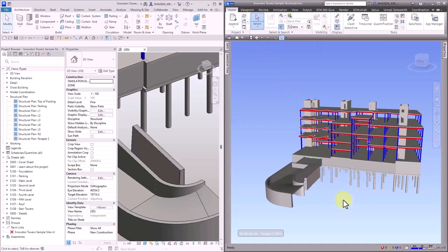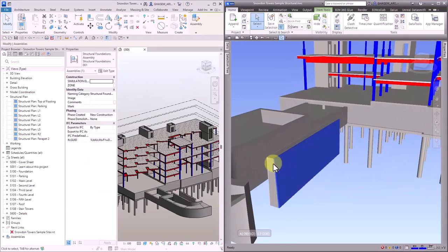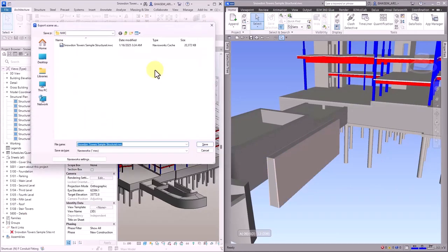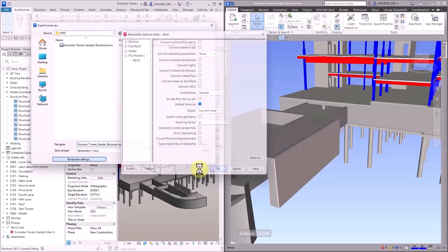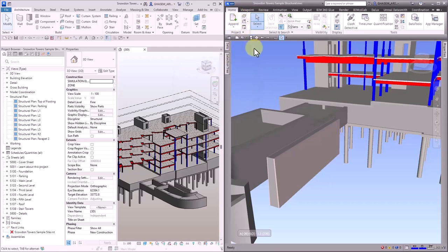You will see that it is updated, and very easily we can have different parts of this element here. So if I return to Revit, NW, and inactivate this item, OK, save. We'll wait until this exporting is done. And if I click on the refresh icon in here, you will see we'll have the main geometry in here.